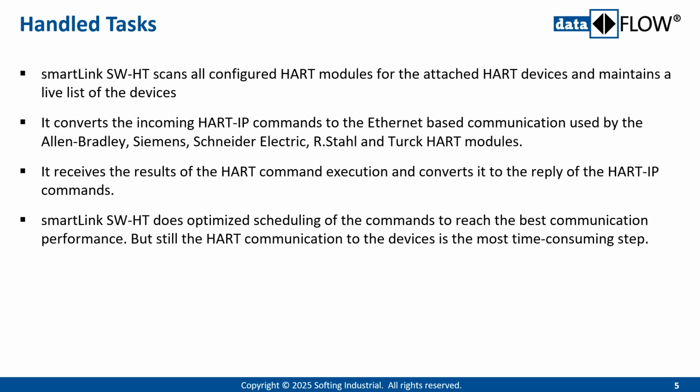So to summarize, the SmartLink SWHT is fulfilling quite precise and defined tasks. The first thing is that on startup, it scans all configured HART modules for the attached HART devices and creates a live list of all the devices connected. We will see later on what you have to configure.